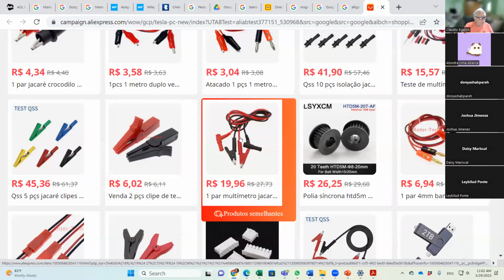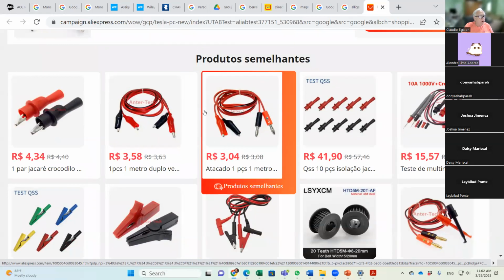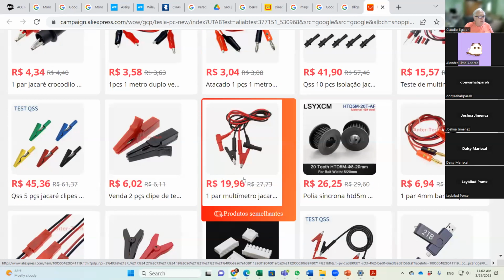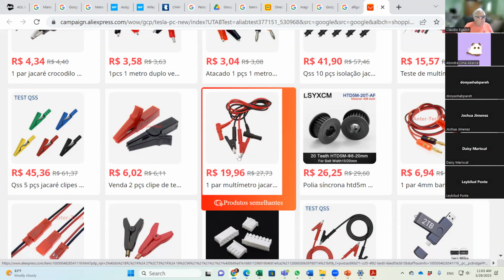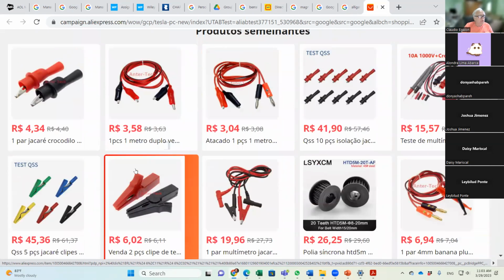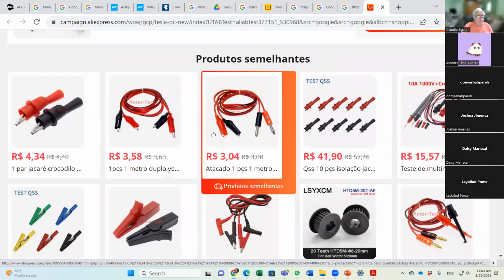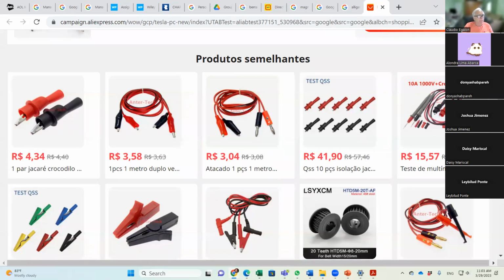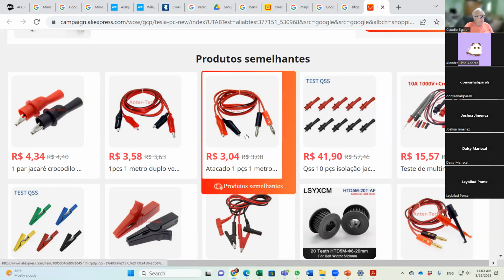That's another way, which is a more expensive alligator clip. It's fancy. I don't like this one; we have only those ones there in the lab. This one is nicer too. See that? It's more sturdy. Here's another alligator clip, a different one, just to grab the end of the resistor. This end goes to the multimeter: red to red, black to black. Plug in there in the multimeter and you take the measurement. Secure the alligator clip.